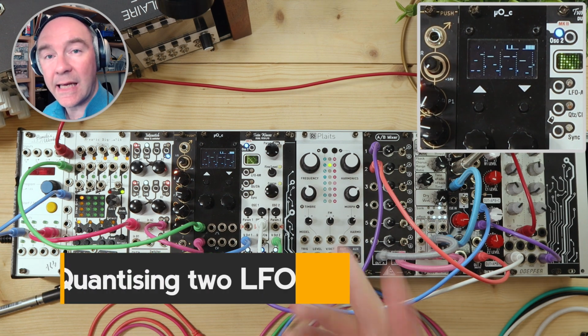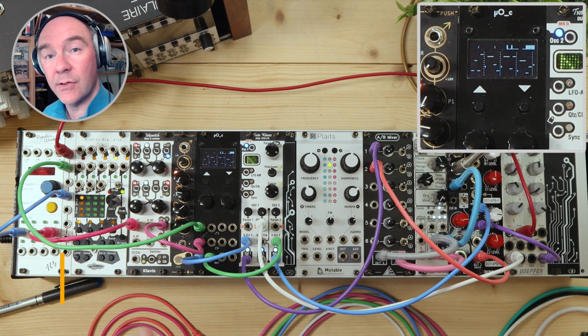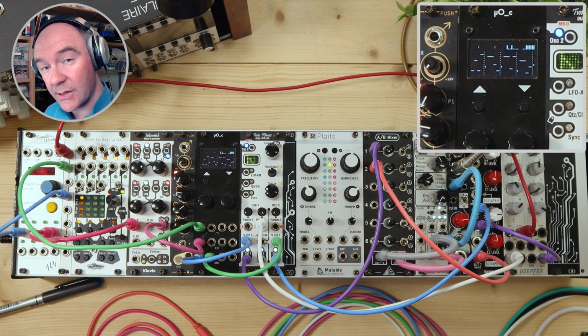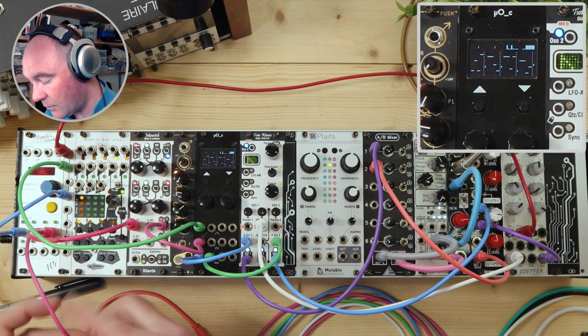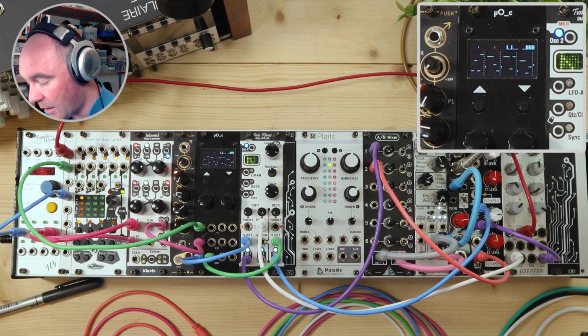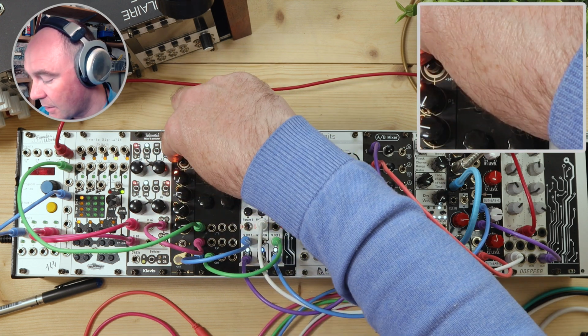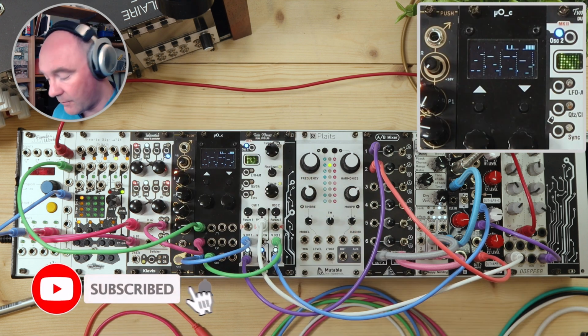Now let's add a second LFO into quantiser B and use that as the source of the notes to quantize. So I've got a second LFO, a slower sine wave on output 3 here. I'm just going to patch this into the B attenuator on the mix switch, and I've set the A attenuator into negative mode, so I can pitch down now with this as well. I can subtract from the voltage.